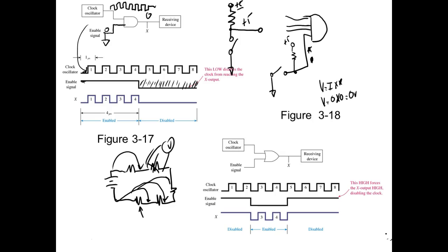Why? Because nothing in the circuit is dropping a voltage. That's why I go over here and open this light switch over here. What would I measure across that light switch if I open it? The applied voltage. Why? Because these lights are not dropping a voltage, because there's no current flow through them. Right? How much would I measure across the switch if I close it?